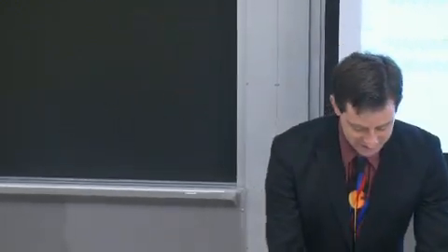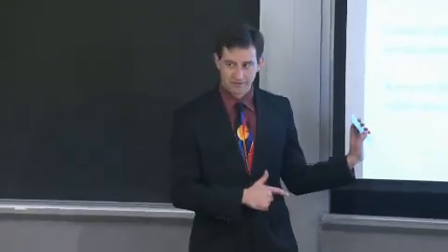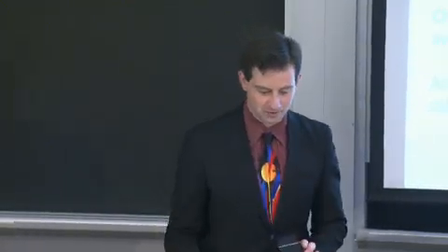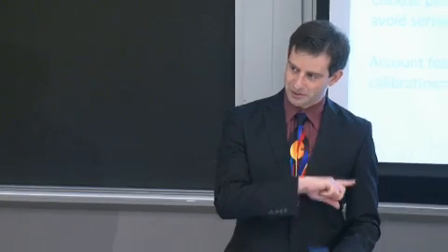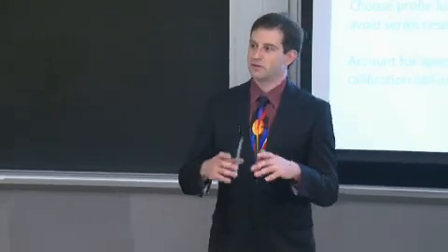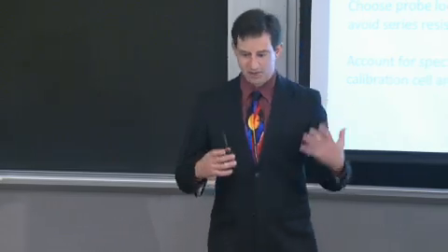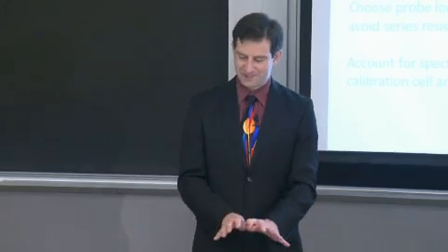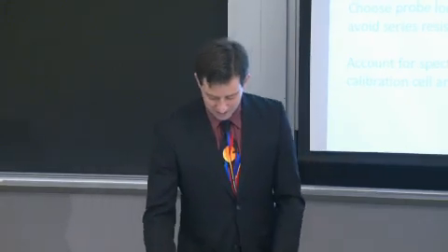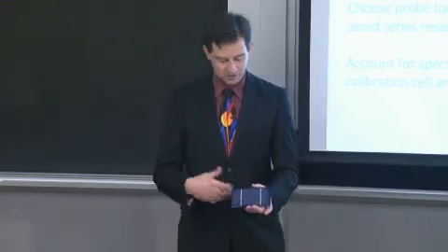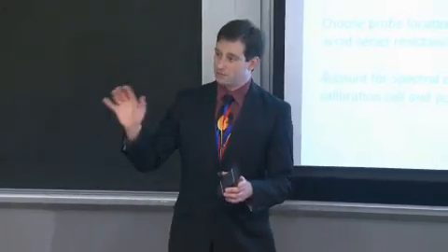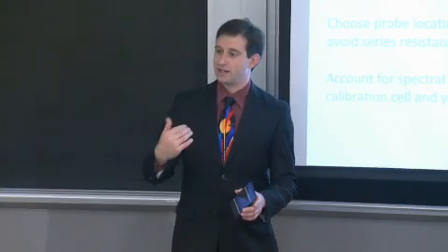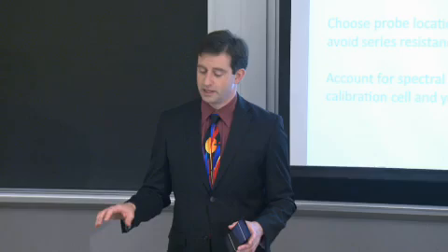Yep. So there are a lot of things. Let me spend a minute waxing poetic about the discrepancies between these cell efficiency measurements and what actual cells experience in the field. We understand the logic behind cell efficiency measurements. We understand that we have to have a universal way of comparing a cell in Japan, in Boston, in Freiburg, Germany. So we need some standard method of cell measurement. This cell measurement proves very useful when you measure the output in terms of peak watts, because then you can multiply by the number of peak hours of sunlight per day and estimate the energy output as a function of location on the Earth. So it has its uses.